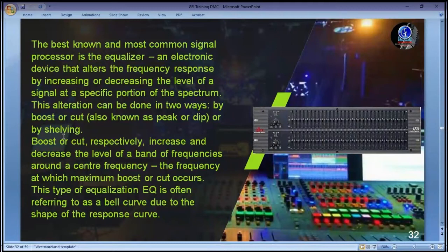If your voice is shallow, or maybe you have too much sibilance on your microphone, which frequency is responsible? You look towards the 10K to 16K to 20K. That's where we have those sibilances. You have to go there and cut down. If you don't understand the frequency response, it will be very difficult, I'm repeating it, very difficult for you to operate an equalizer successfully, because you must know what you are equalizing.